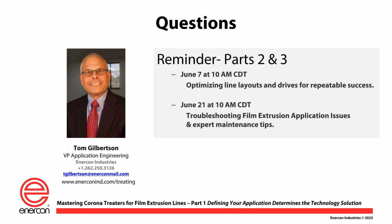So again, let's say we're trying to dissipate this 10 kilowatts on this 2 meter wide line. If I have to dissipate 10 kilowatts, I'm going to have a mass of metal out there to get rid of it. I have to design the treater station in a way so when you turn it up to 10 kilowatts, the entire electrode can dissipate 10 kilowatts.